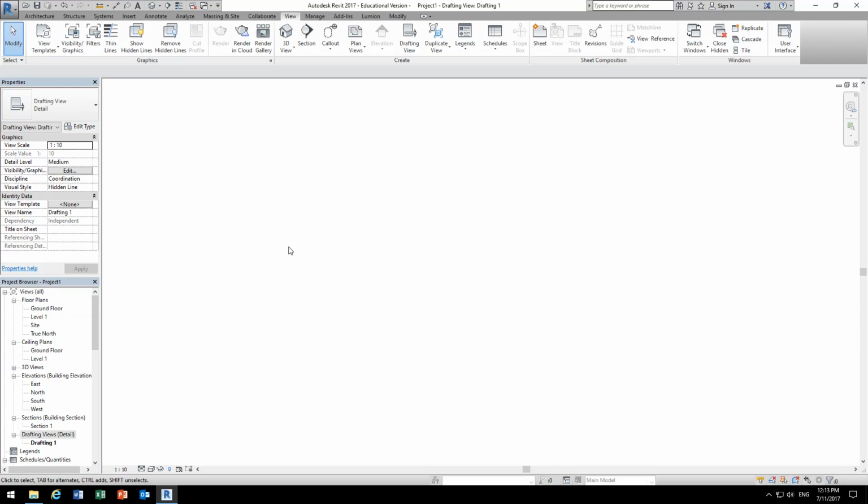So you actually did that with the AWS AutoCAD one. You had the drafting view, imported the drafting view, and did that, then grouped it. Yeah. And it works, but that means that the file stores those lines over and over again. It gets really big. You exploded it, but only partially exploded. So we ended up with like a transom head and the bracket all separate, but we didn't completely explode it, so it's sort of controlled the size a little bit. Yeah. And it works, but if you make a detail family, then it only stores it once, and then it just stores the insertion point each time it's inserted. And so that's just a file management thing.